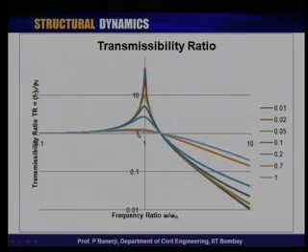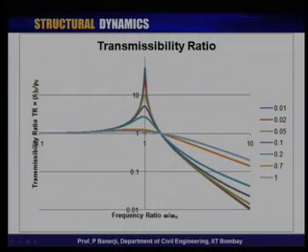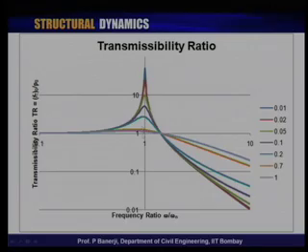In other words, build huge damping into the system such that the transmissibility ratio remains as close to 1. Look at it: almost make it critical damping, to ensure that you see 0.7 and 1 are very close to each other. 0.7 is under critically damped, 70% damping. So, you need to introduce huge damping into the system to ensure that the transmissibility ratio remains low.